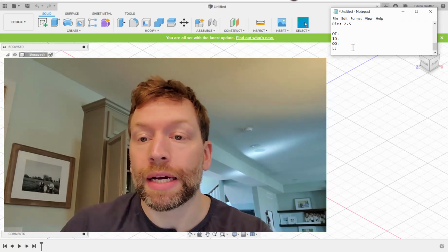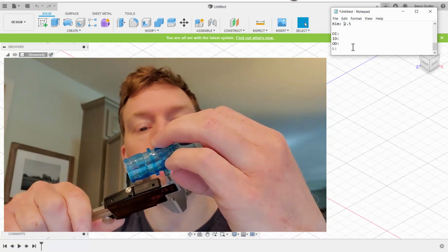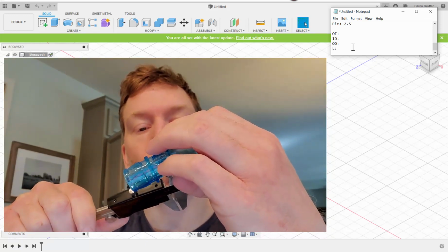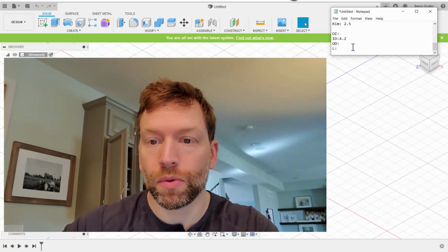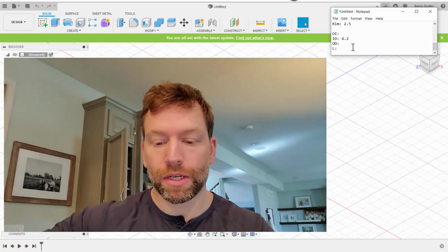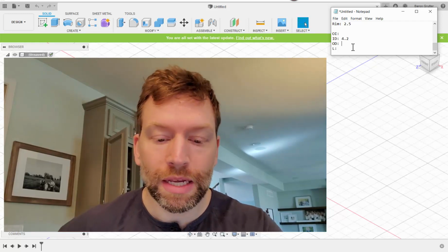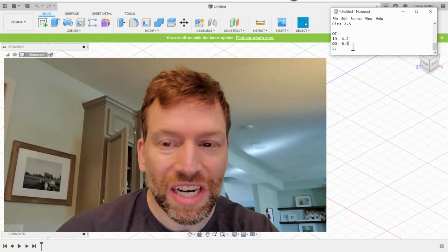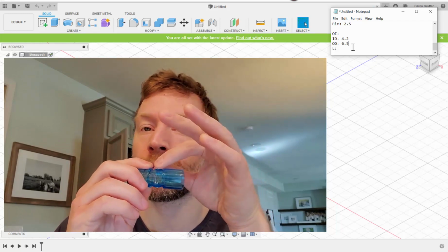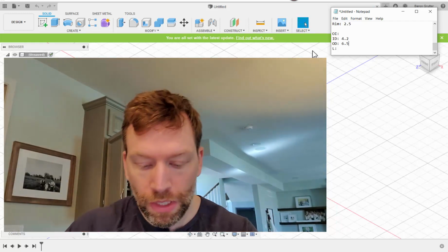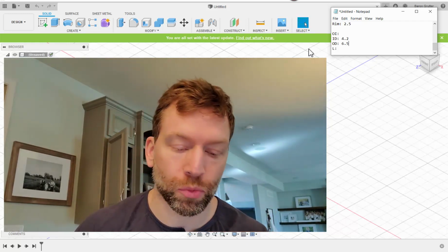So, okay, now we've got the oxygen inlet. Let's see about the diameter. These really small diameters are a little bit tricky to measure sometimes. This isn't too small. So it's 4.2. Outside diameter, 6.5. It was just shy of that, but I'd rather go a little higher. I will tell you that these adapters, all rubber hose attached to it, so I'd rather go a little bit higher because I know that it will slide over top. These parts are always going to be plastic. They're not going to be quite as flexible, but we'll manage.